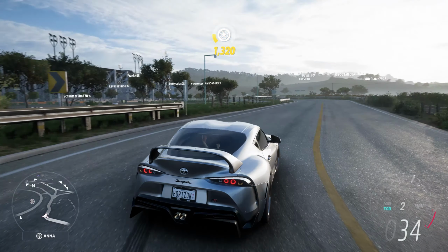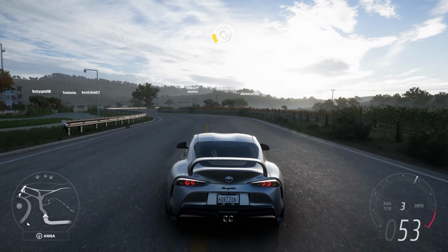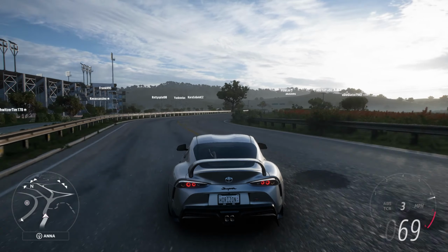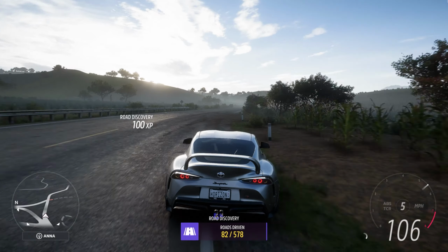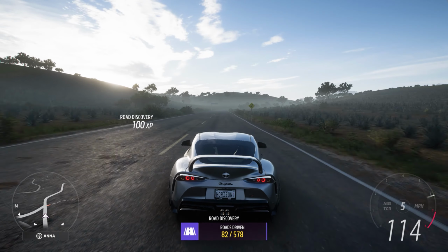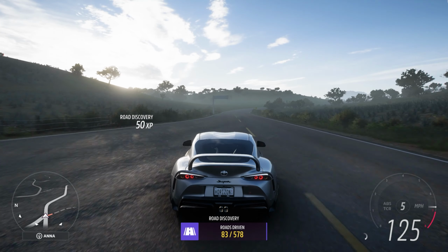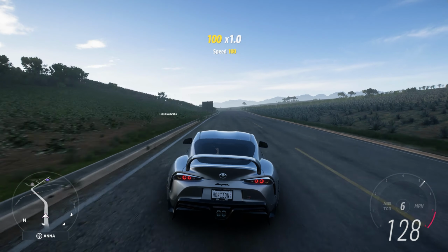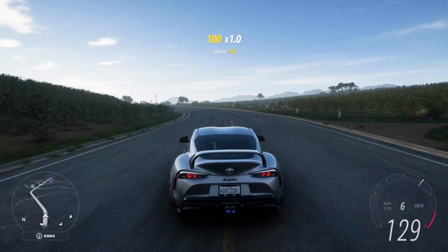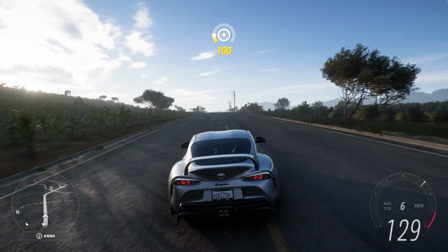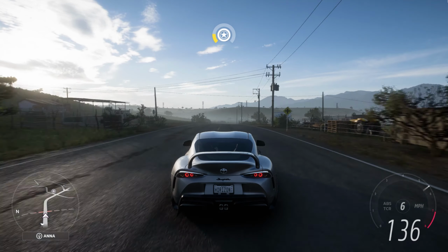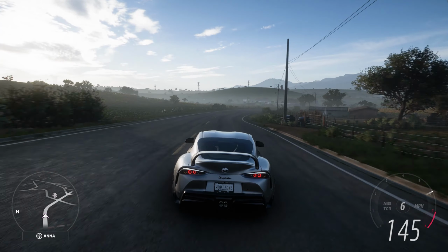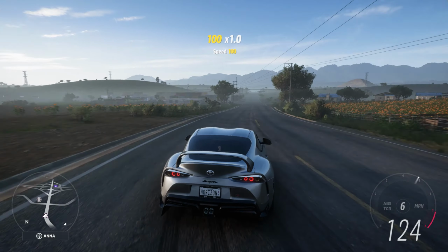We have three major types of throttling. Power throttling represents a situation when your CPU temperature is below its limit, and in order to reach its maximum frequency, the CPU wants to consume more energy than the power supply can provide. Thermal throttling is when your CPU has reached its temperature limit, staying below its power consumption limit. And the last one is when we have both types of throttling together.